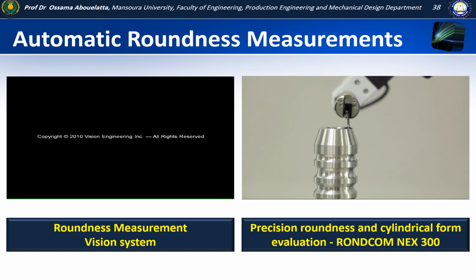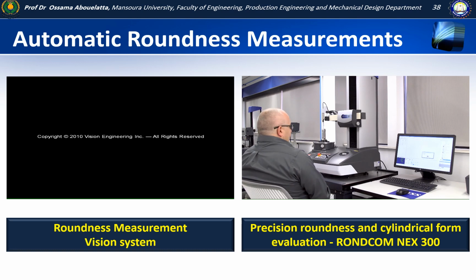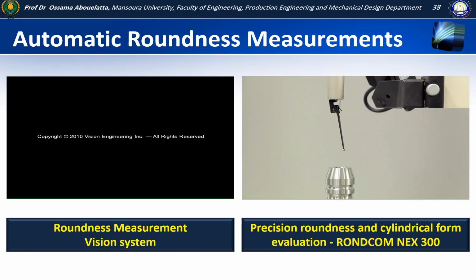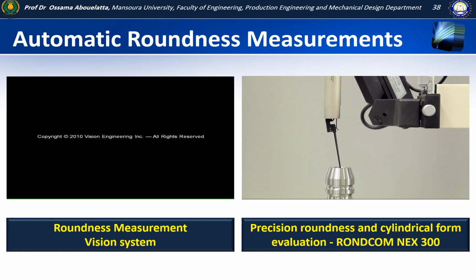From here we are taking a flatness trace on the top of the workpiece, and from here we move to the inside and do an ID measurement. The ActiPro software comes equipped with the latest standards and settings for form and finish measurements. ActiPro also has the ability to find edges of workpieces to form a part coordinate in R or Z axis.